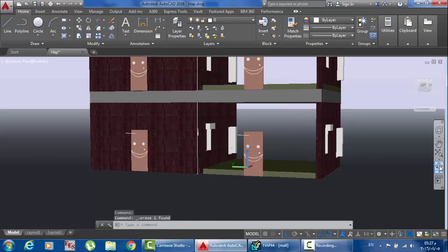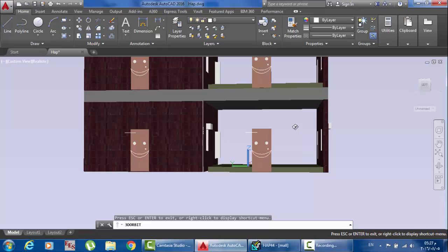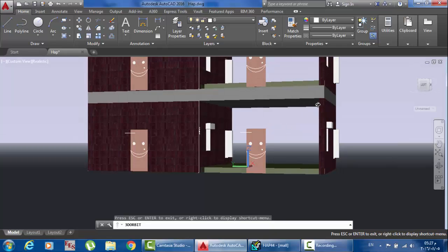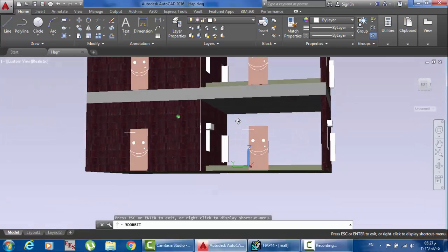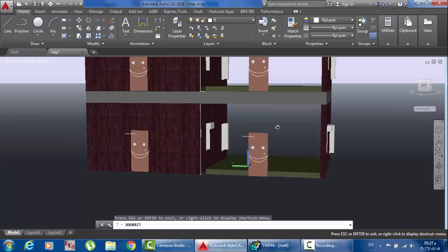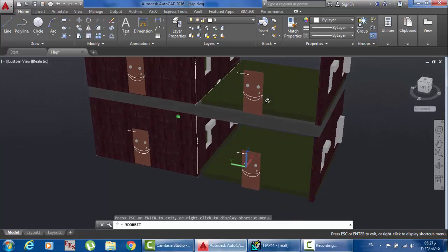And here the ceiling. The ceiling is the inside area, and it is not exposed to the sunlight like the roof. You can take the full area of the ceiling. It is actually the same as the area of the floor, but suppose that the upper zone is not like this. You may have the half of the area.